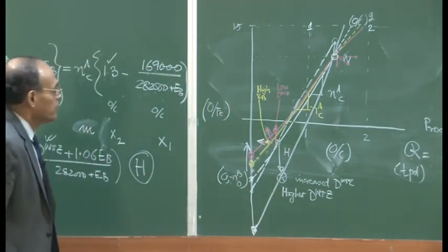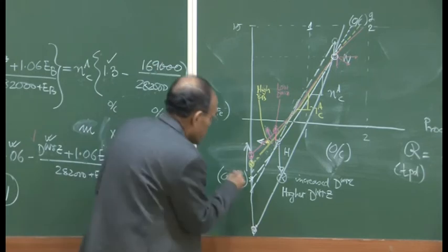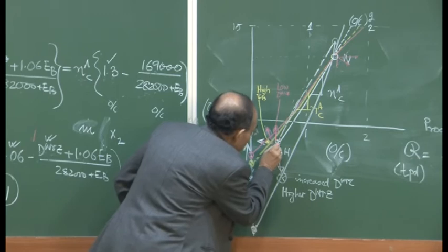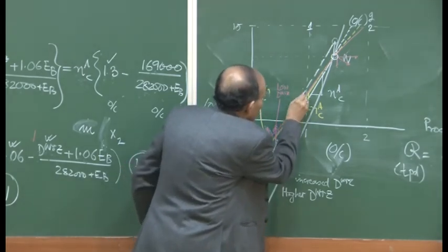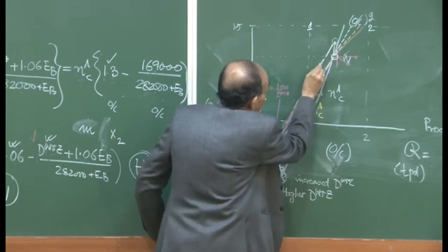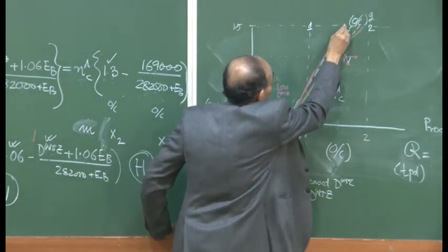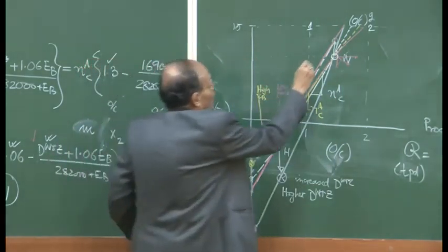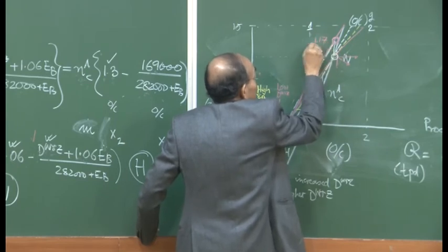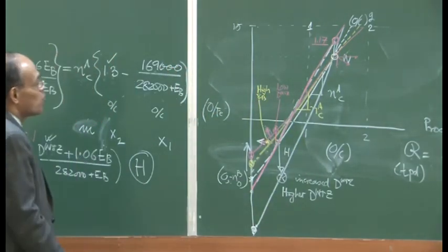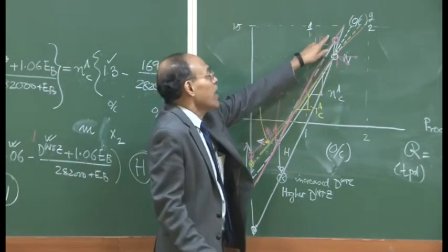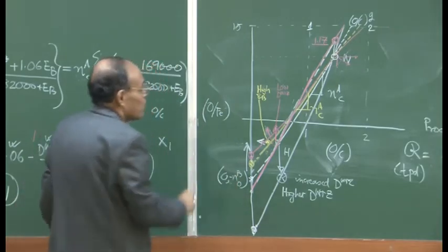I can draw this line, where the enthalpy remains fixed, and now we have more impurity in the ore, which means the 1.06 factor now becomes 1.17. Say with silica reduction, manganese reduction, phosphorus reduction and so on, just metalloid reductions, this point from 1.06 has become 1.07 and the line has become more steep.